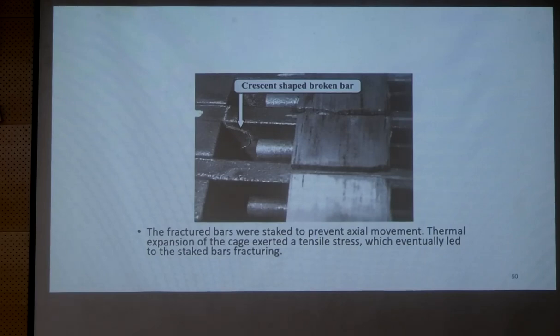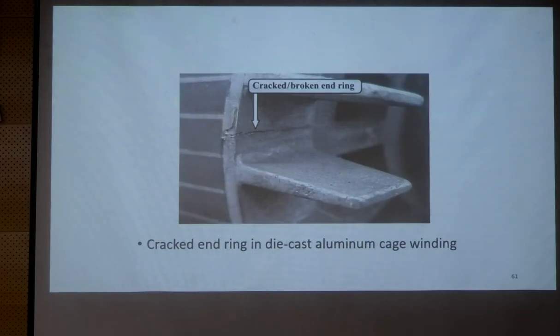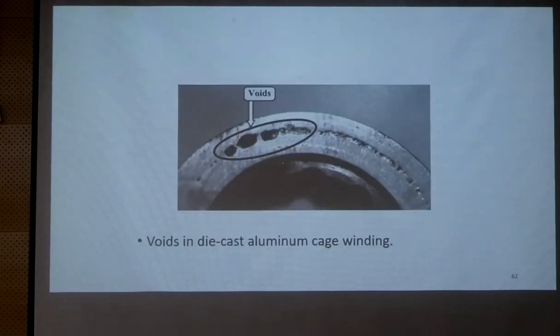You can observe cracked, broken end rings. These are some of the references I have taken. You can see the void; this will affect the particular pattern, the particular signature you get with these types of problems.